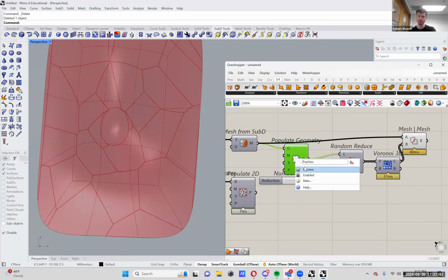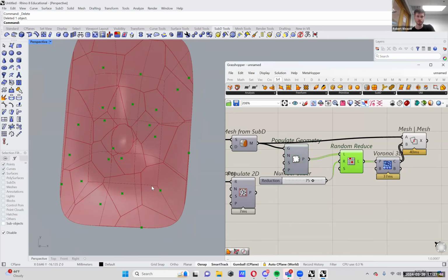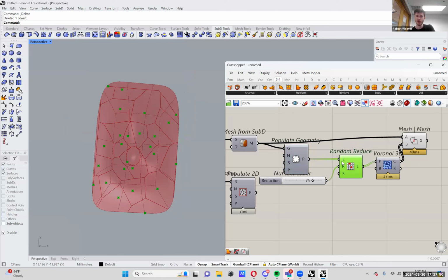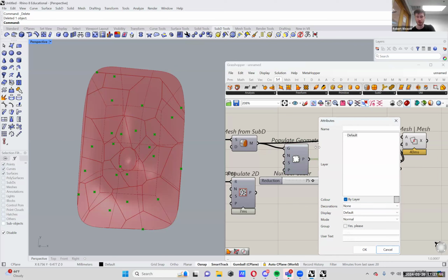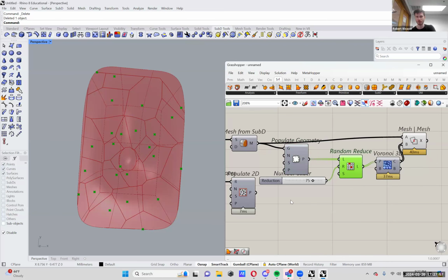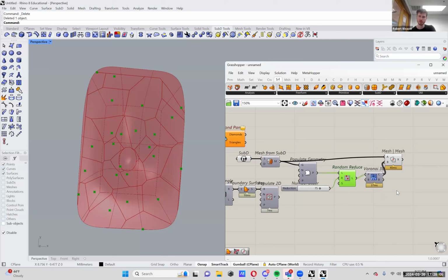But it's really up to how you set the point system with how the Voronoi is going to be produced. You could even use Grasshopper to set some points, then bake these points and manually push them around a little bit to control the pattern to exactly what you want. That could also work really well. So I'd probably say start with SubD, see where you can get with Voronoi, and then maybe next week we can look at improving on what you have.